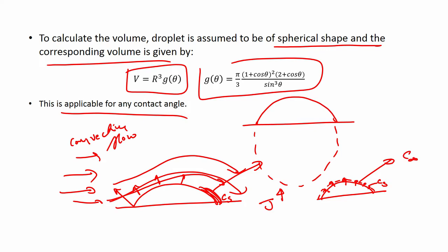So basically you get an enhancement of J just because of the Reynolds number effect, and this will be particularly useful when you start looking at the scenario in the case of a contact free droplet, okay, where the effect is much more prominent. Okay. But the evaporation mechanism is the same, but the transport mechanism which determines the J, that is different. Okay. But it is still given by the Clausius-Clapeyron equation, that what is the vapor flux or the concentration of the water vapor or whatever vapor that you are dealing with close to the surface.